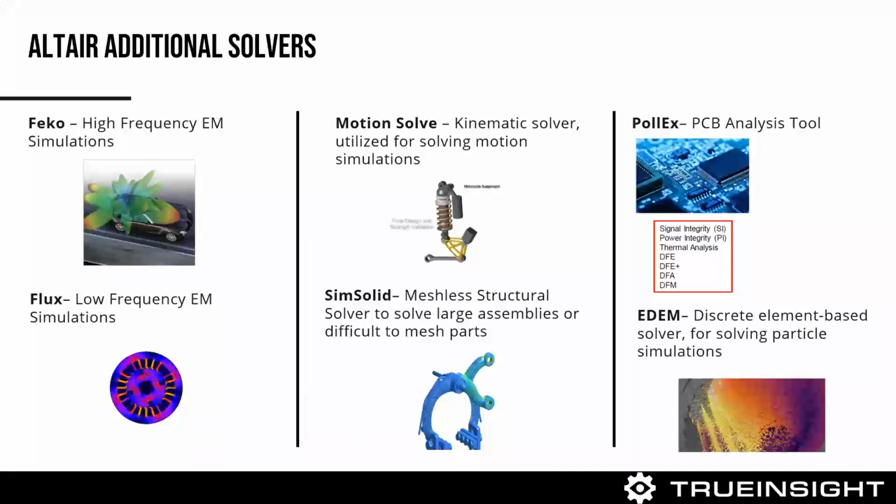So Flux would be our low frequency tool. Again, it's another electromagnetic simulation tool. It's using a finite element based approach, so you mesh a system. For those of you designing motors in the EV space, this would be a great tool for you because you can simulate those electric conditions, but also the thermal conditions. Maybe you're looking at the heat that would be generated in a charging cable for your EV vehicle. We can simulate that.